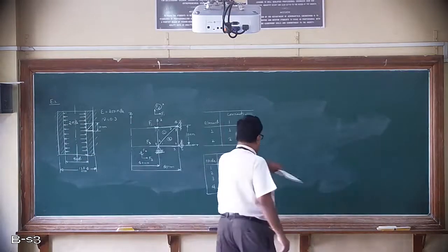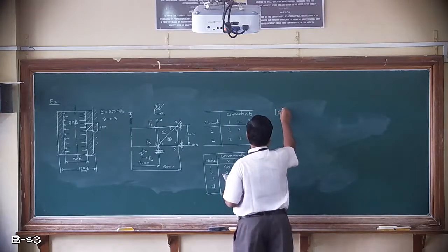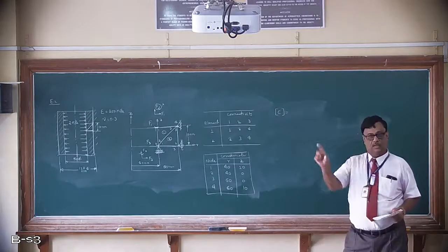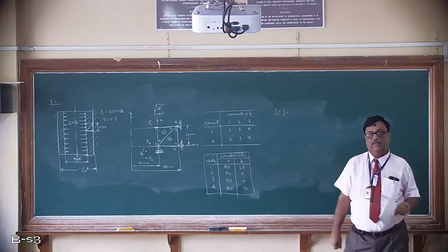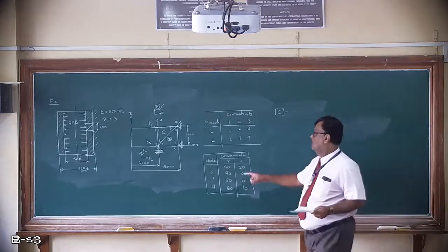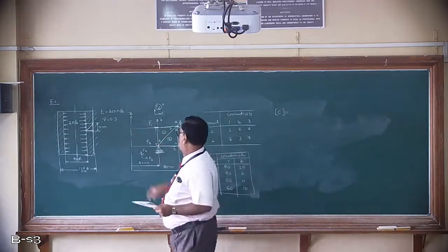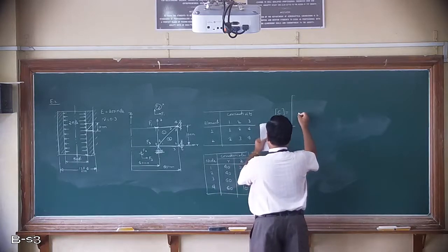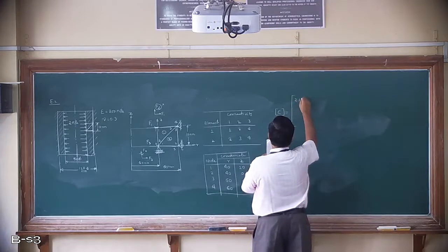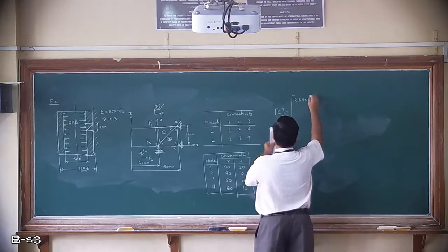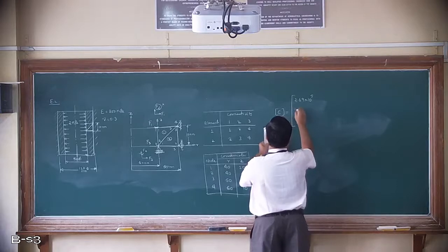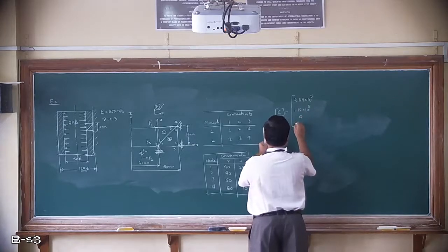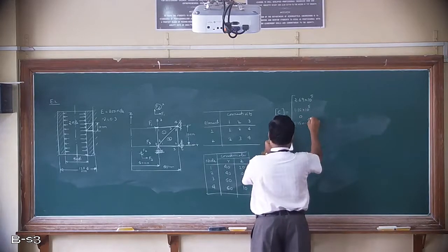And I have already given you the expression for the material property matrix, in the previous class, how to find the 4 by 4 material property matrix. If we substitute the Young's modulus and Poisson's ratio given there, I will directly show you what we get. The first row is 2.69 into 10 raised to 5, 1.15 into 10 raised to 5, 0, 1.15 into 10 raised to 5.